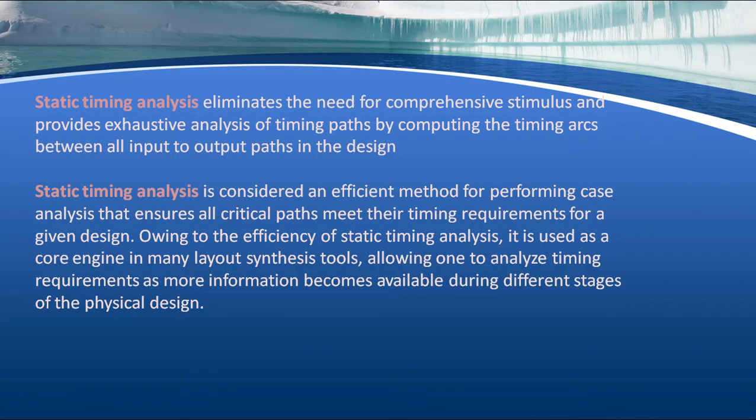See, static timing analysis eliminates the need for comprehensive stimulus and provides exhaustive analysis of timing paths by computing the timing arcs between all input to output paths in the design. So there are many different paths from input to outputs.